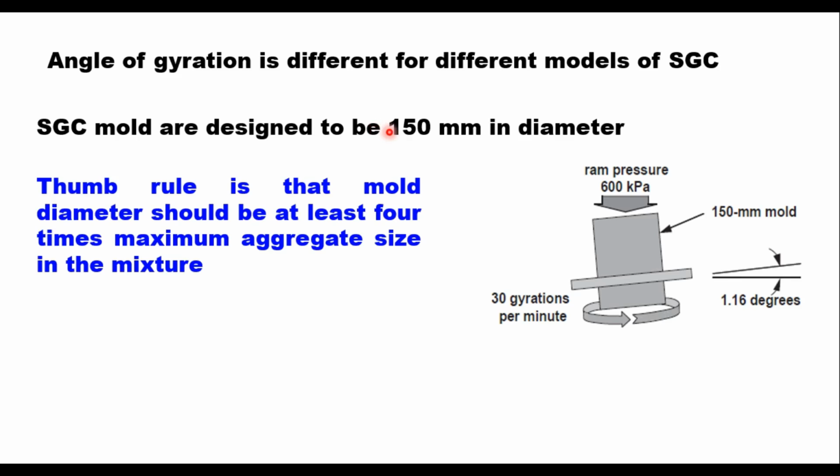Although all parameters need to be regularly and accurately calibrated, the gyration angle has the greatest effect on specimen compaction. As the angle increases, the compaction effort increases, and similarly, if the gyration angle decreases, specimen compaction will decrease. Relatively small changes in gyration angle can make significant changes in the compaction level. And AASHTO has developed a procedure for evaluating the internal angle of a gyratory compactor. This should be used to check the gyration angle of the compactor, particularly when there are different compactors in the field and in the laboratory.